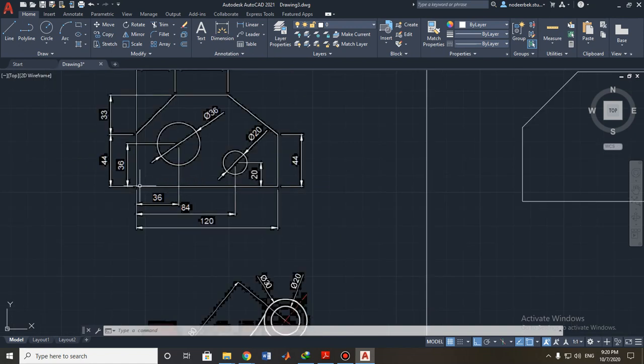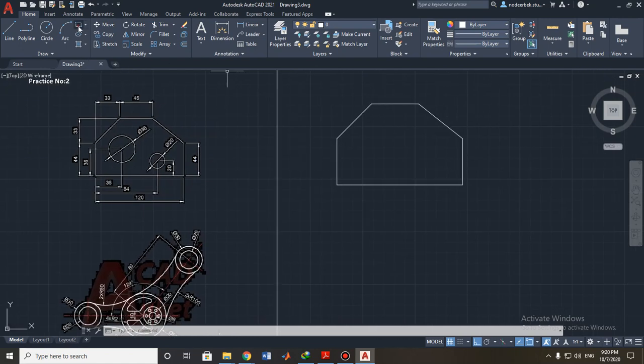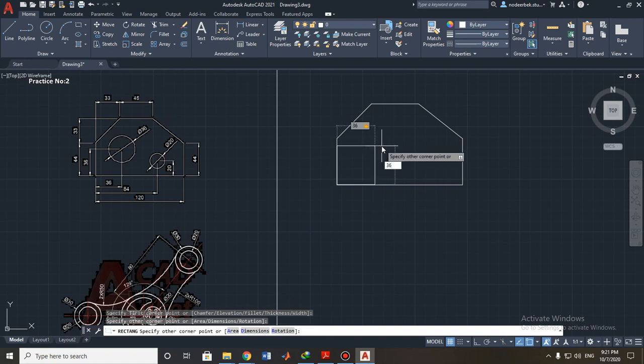So now we can build here one helpful square, and then we need to choose the center of this circle, and we will build this circle here. Okay, let me do this. So I will choose the rectangle tool. Now we will start building a rectangle from here, so it will be a square. So as you know, the horizontal side and vertical side are the same, 36 millimeters. I will put 36. I will press tab, and then 36. Now I can press enter.